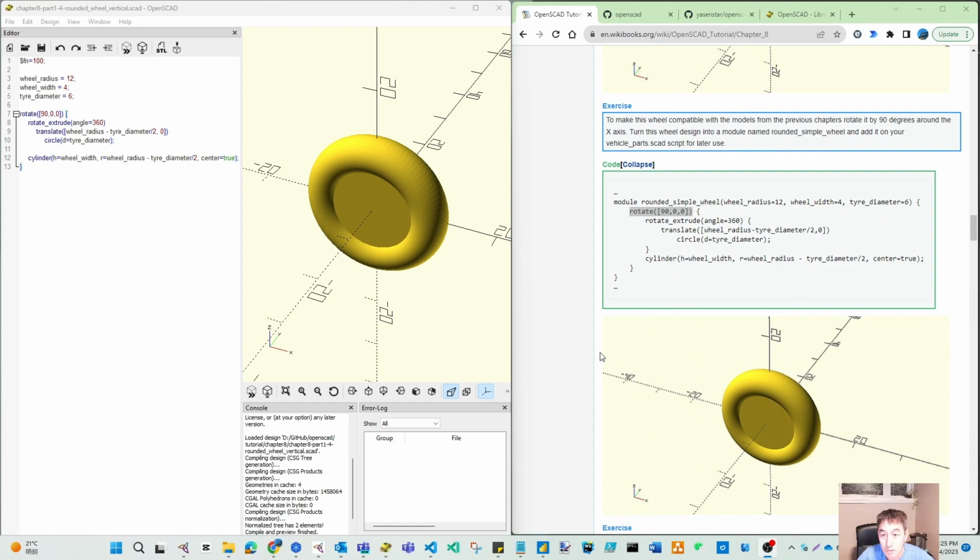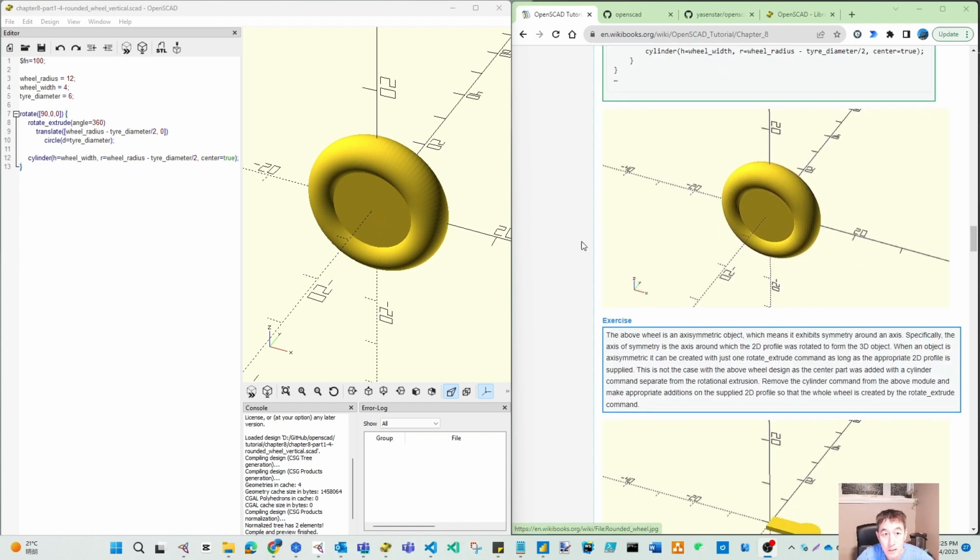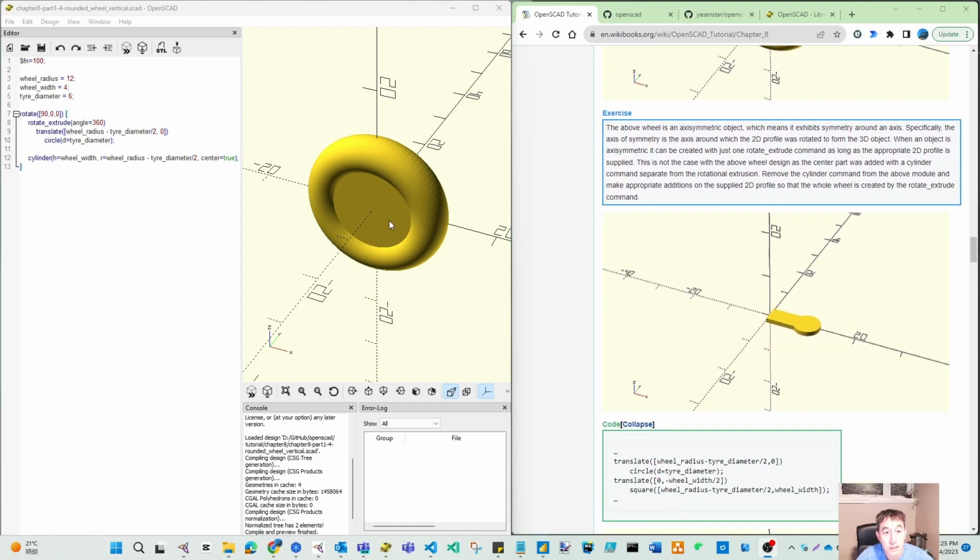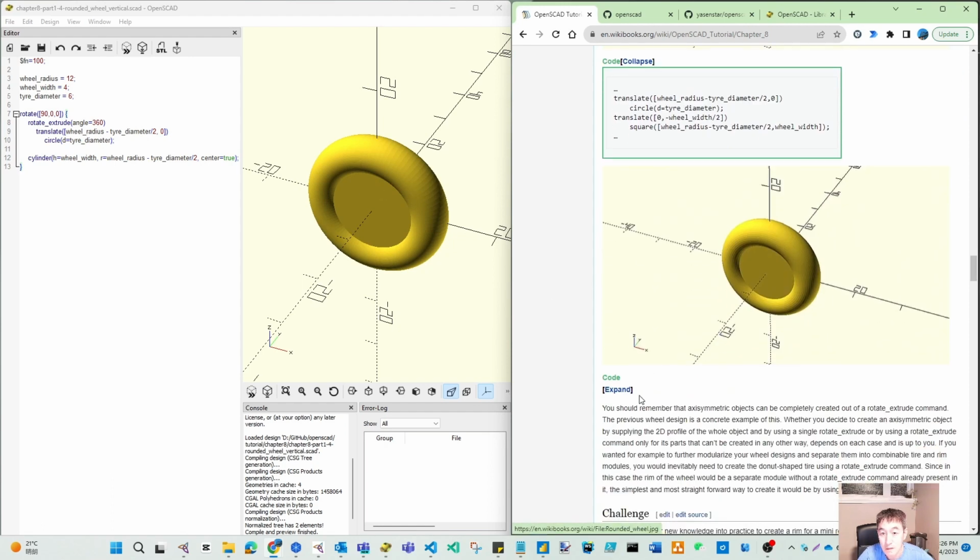If you read the paragraph, we made our circle, did the rotational extruding, and then inserted our 3D object. It's a cylinder. But when you examine this finished 3D object, it is a symmetric object. Whenever you identify an object of this type, it gives us a possibility: we can create the purely 2D shape first, and just use one step of rotational extruding to get this finished result. So let's do this together.